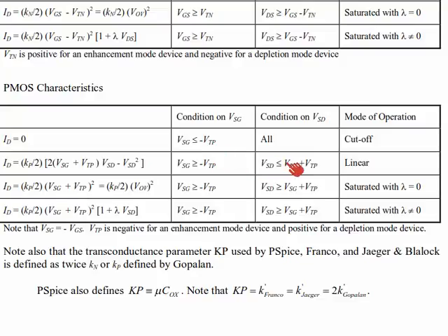Then to distinguish the linear and saturation regions for a PMOS transistor, we would compare source-to-drain voltage with the pinch-off voltage, source-to-gate voltage plus VTP. Smaller VSD compared to the overvoltage, the pinch-off voltage, gives us linear mode. Greater VSD gives us saturation. The current-voltage characteristic equations look the same. We just switch the subscripts on VSD, VSG, and make the sign before VTP positive.